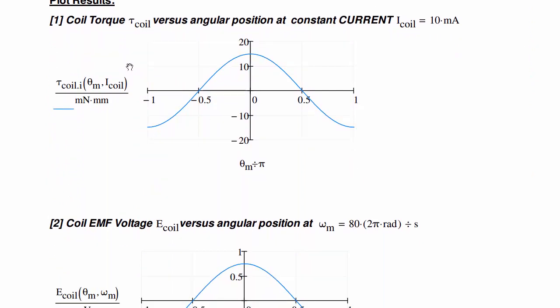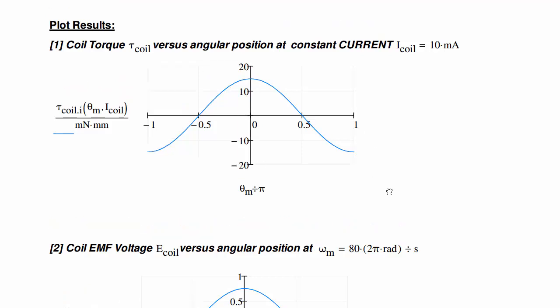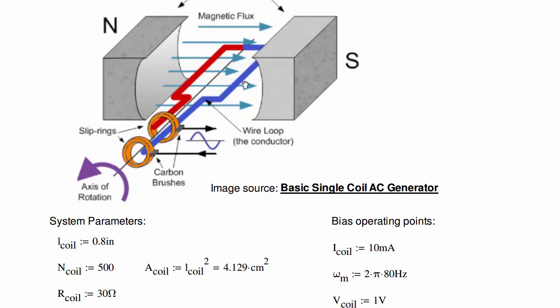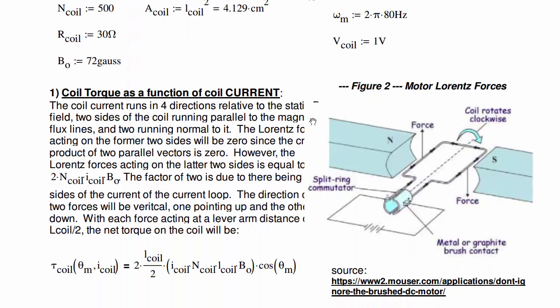So starting back from the first equations and moving through that, I've plotted everything here for a visual. So we're plotting motor coil torque as a function of rotor position. Everything here is going to be as a function of rotor position. And the zero angle, maybe I should go back, the zero angle is this angle right here. So at an angle of 0, the flux through the coil is 0, and if we also look at the torque applied to the rotor or to the coil at this point, it'll be maximum. Notice it's this scenario here.